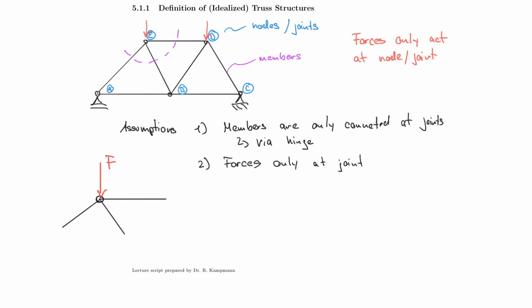So there's F. And then I would have released member forces. So for example, I released AE here, right? AE comes from node A to node E. And so this is this one. And then I also have BE and DE. So let's include that. BE and DE. And since I cut them here, I now have the node just individualized.